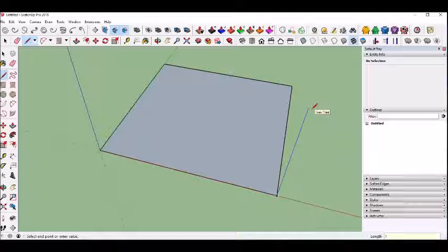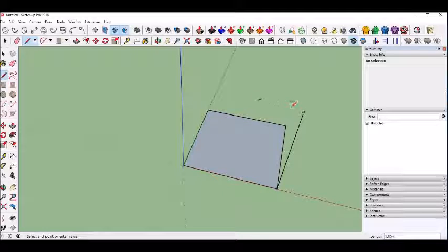Okay, 25. Okay, let go of Shift, hold 20, hit 25, and hit enter. Zoom out. So now we have a line. So now let's go along the red axis. A couple ways we can do that. You can hover on the red axis, and it'll show it there.